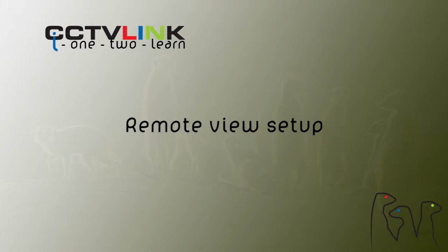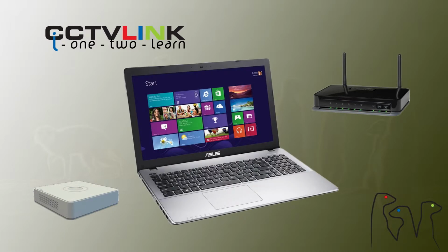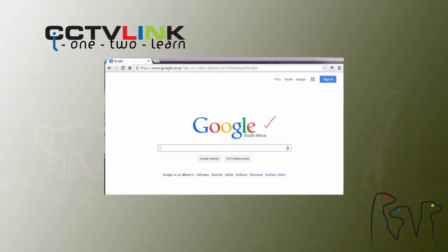To set up remote viewing on a DVR, you need a network cable between the DVR and the router, internet on the same router, and a laptop or PC to set up the port forwarding. Let's get started. Make sure your DVR and PC are on the same network. Open the browser on the PC, and make sure the internet connection is available.